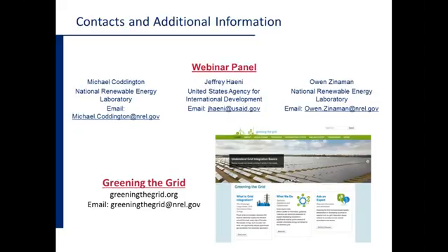And if you end up losing, say, 40 gigawatts of photovoltaic system pretty simultaneously, then you would see the frequency crash downward or start to drop dramatically, causing another problem where they start to take out wind systems that drop off at low frequency. And so Germany has had to, again, spend a significant amount of effort and actually send people out to reprogram inverters at a very high cost. And that's a lesson that I think we're all watching and trying to make sure that we don't repeat.